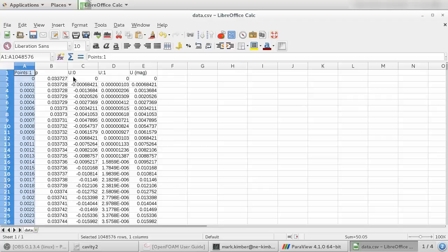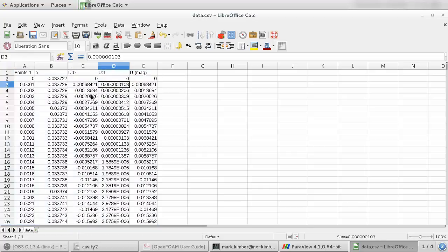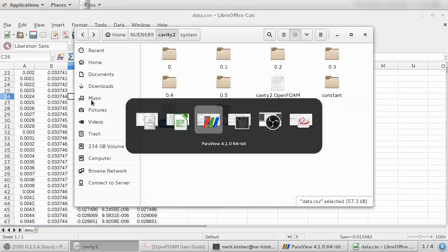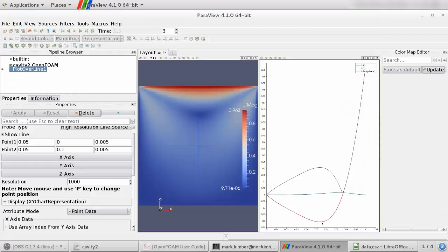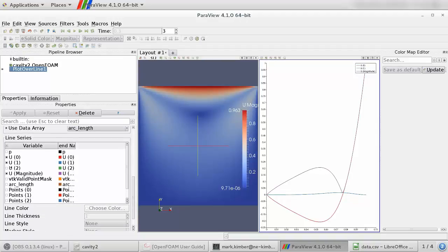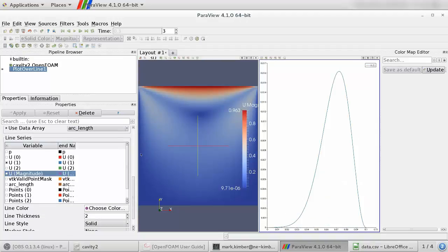So now I can plot these, and I can do GCI studies, for example. If I wanted to look at the maximum of the x velocity, for instance, I could take any of these points here, maybe the minimum of my x velocity, or the maximum of my magnitude, or maybe I could even take a look at the y. Maybe the y velocity is the one that I care about. Maybe I want to do a GCI study on the peak value found from this.